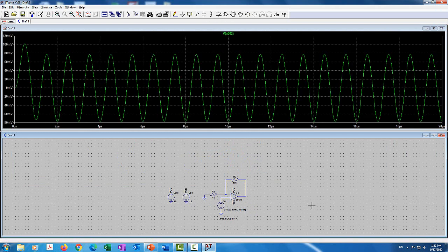A couple of things you need to see is that early on the circuit hasn't settled yet. We call it the transient effect. So that's something you need to watch for, the transient effect. But over here it's settled, it reached the final value. And we can see that the gain over here is not a gain of 20. It's much lower.